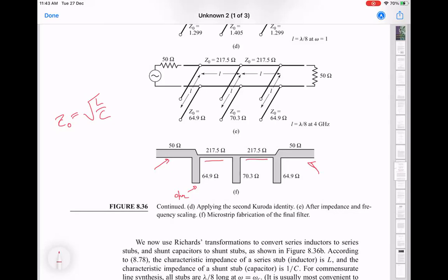It's not contained in the simple model, right? The LC ladder network is always going to give you the perfect transmission line equation, irrespective of the values of L and C. But that's an approximation. The problem is that you're ignoring the fact that there is free space around it, when you're saying that all the electric fields are confined between the points of the transmission line, with just some spread around it. But if you just have a very thin piece of wire, then it can actually start to radiate into free space. Okay.